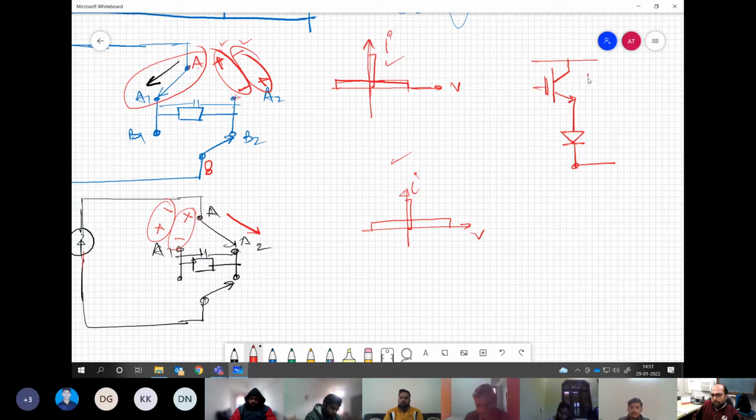The direction of conduction for both the devices is the same. So we have one direction for the current to flow. Whereas if you talk about the blocking voltage polarity, this device can block voltage in this polarity and the diode can block voltage in this polarity. So we have bidirectional or bipolar voltage blocking capability. Understanding my point? Yes, sir.